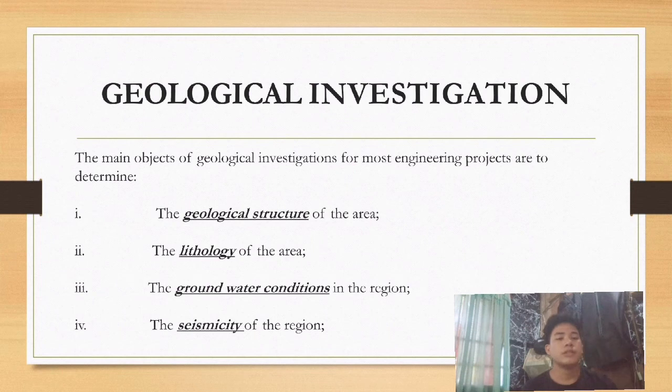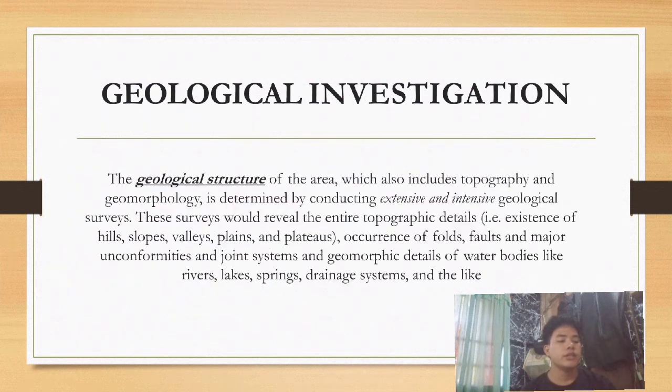The main objectives of geological investigations for most engineering projects are to determine the geological structure of the area, the lithology of the area, the groundwater conditions in the region, and the seismicity of the region. The geological structure of the area, which also includes topography and geomorphology, is determined by conducting extensive and intensive geological surveys.